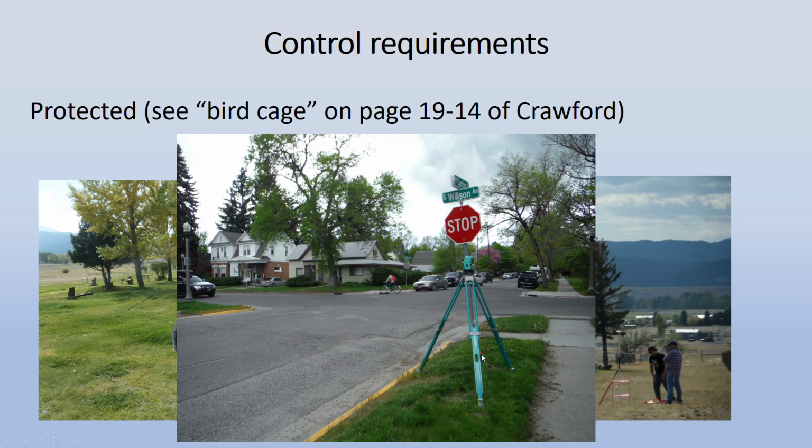So actually this one's kind of hidden by the tripod leg here, but my traverse point, I simply put a little pin flag. You can kind of see the pink there of my pin flag, just so I could find it the rest of that day, and then I took that pin flag out. I'm the only one that knows where this thing is, and it's set low enough that a lawnmower won't disturb it, and sometimes that's what you do to protect things.